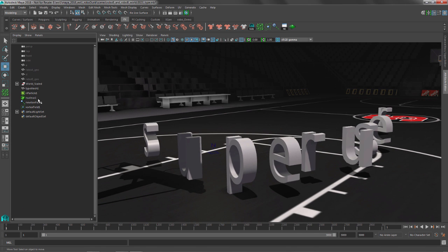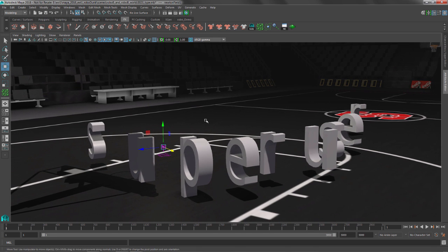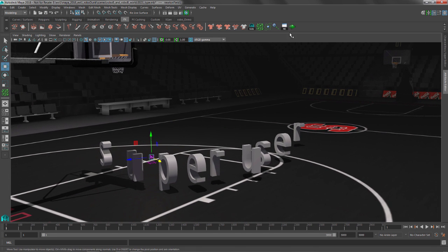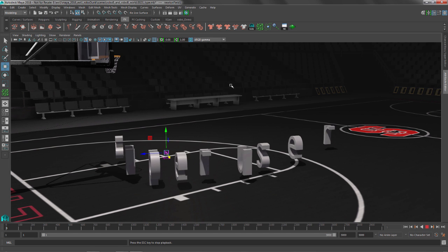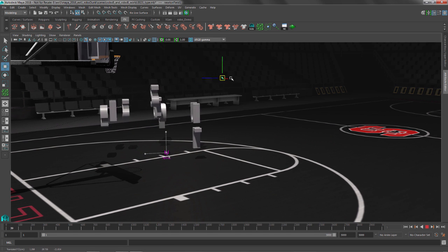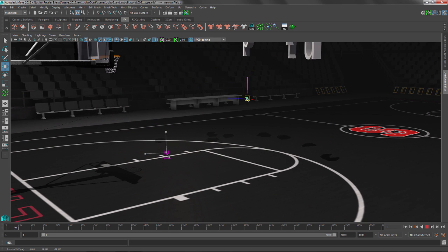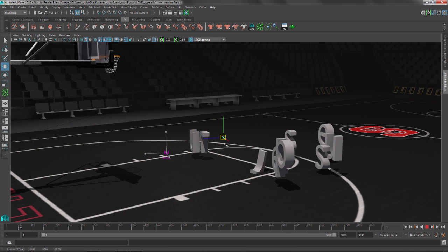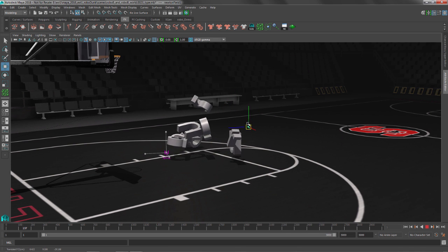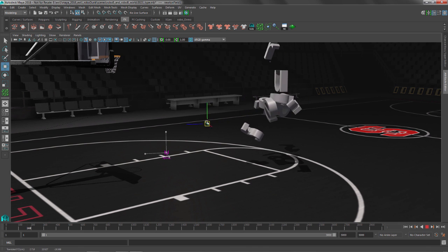grab our Newton field, which is kind of fun to play around with here. And we'll go into the interactive playback mode. And those guys are going to try to get to that Newton field. The vortex is going to spin those around a little bit, and as they collide with the ground, they're going to get a little bit of rotation, and when they collide with each other, they're also going to get a little bit of rotation.